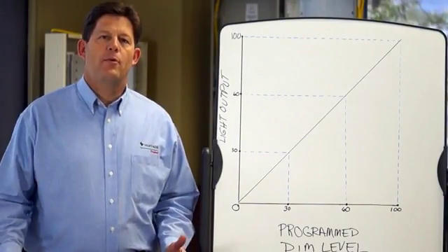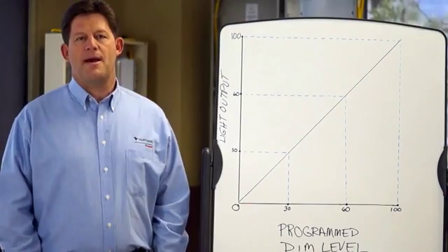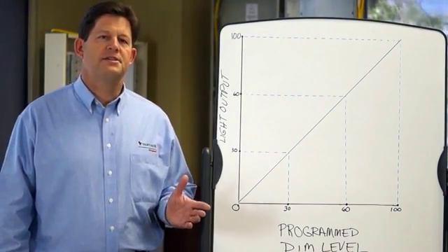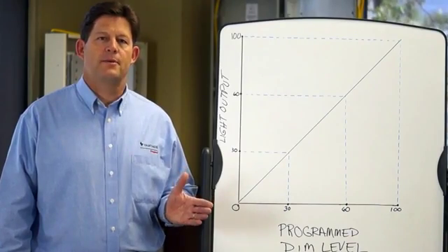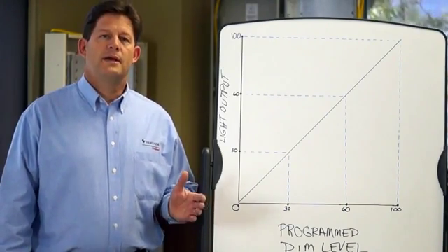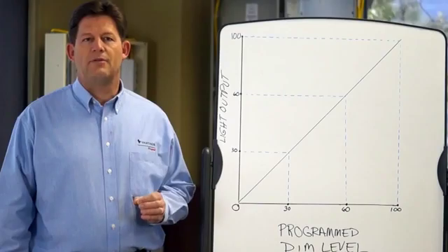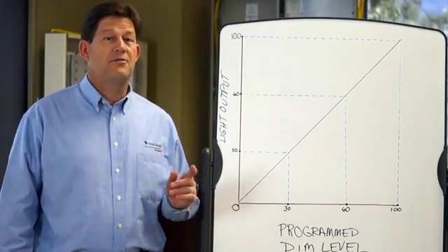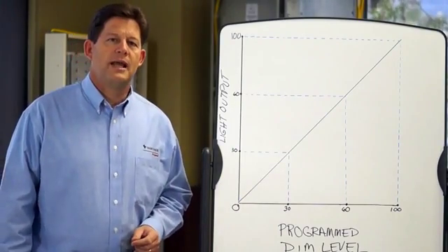At this point, you might be wondering, so why does linearity matter? Honestly, if our lighting control is limited to manually adjusted, unintelligent wall box dimmers, we wouldn't care, because we don't have a marked percentage dim level that we expect to be accurate. We have to adjust to the level we want by using visible feedback of the dim level.